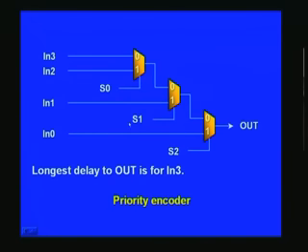On the other hand, if you go to selection of input 1, then it has to go through 2 muxes in order to appear at the output. So is the case with this, and one of these will be the longest path that you will encounter, and that is how you get a priority, but the price that you are paying is 3 delays as such. 3 mux delays are coming into the picture here.